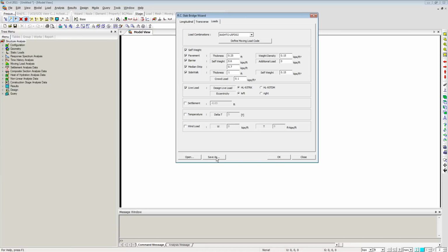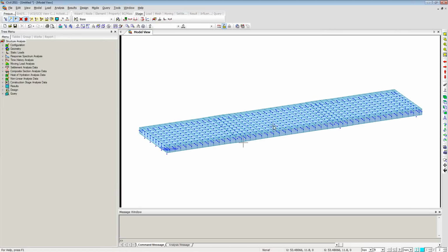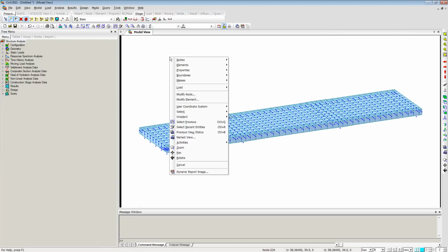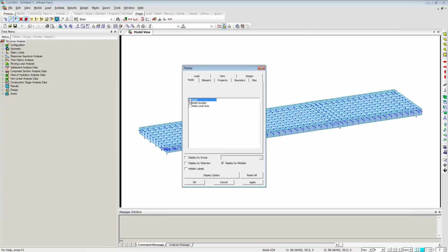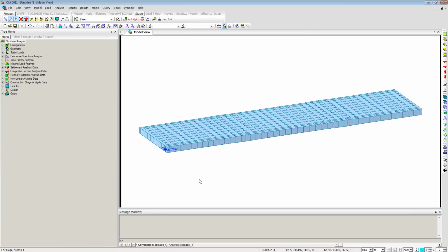Before saying OK, you can also save the model that you created, and just open it later if you want to modify anything. If you want to have like a tube model, the same thing with some modification. Let's say OK, and you have this element. Let me go to display, I don't want to show these nodes because they are annoying.